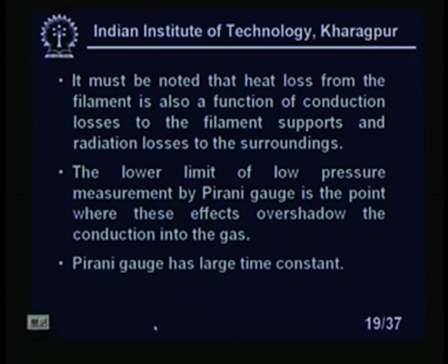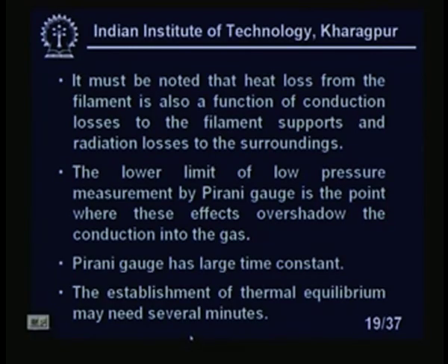Now, one of the greatest drawbacks of the Pirani gauge is that it has a large time constant. The measurement is not immediate. The establishment of the thermal equilibrium may need several minutes, because it is a thermal system, and it may take several minutes before it settles down.